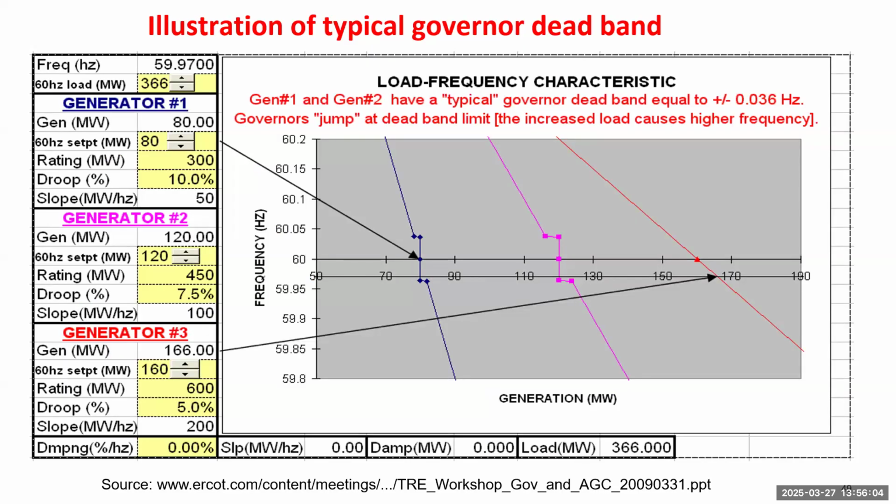So we have 2 additional slides. I just want to give you an idea of how the generations are scheduled and frequency is regulated in real time. This doesn't accurately represent the user interface of operators, but I borrowed these slides from training slides. The training slides are for operators to teach them how to regulate generation, how to adjust the droop control factors, and how to consider the dead band of a generator. So you can treat this almost the same as the software interface of operators.